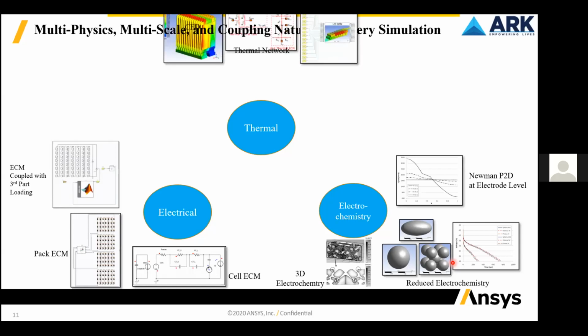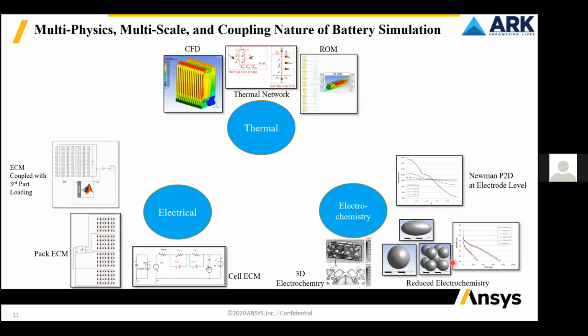Then last but not least in the list is the thermal performance of a battery. Even though lithium-ion batteries have relatively high thermal efficiency, greater than 85%, their sensitivity to temperature makes it critical to manage the temperature correctly. For lithium-ion batteries, it is often required to have an in-cell temperature variation of less than 4 degrees, and the cell to cell variation should be less than 6 to 8 degrees, right?